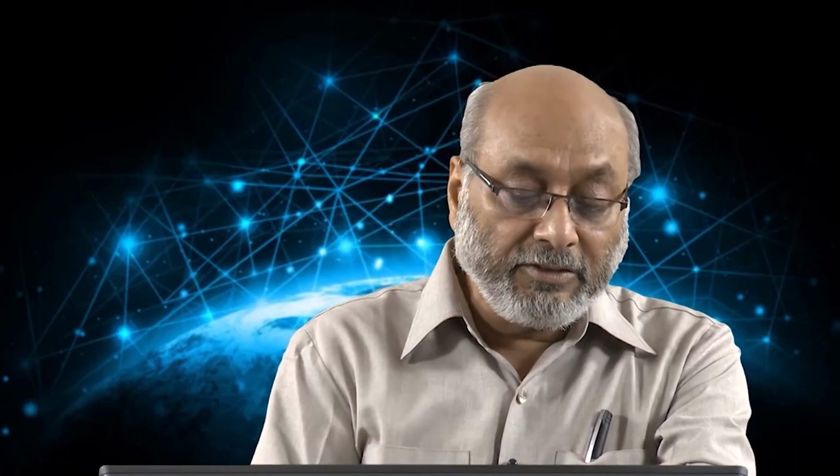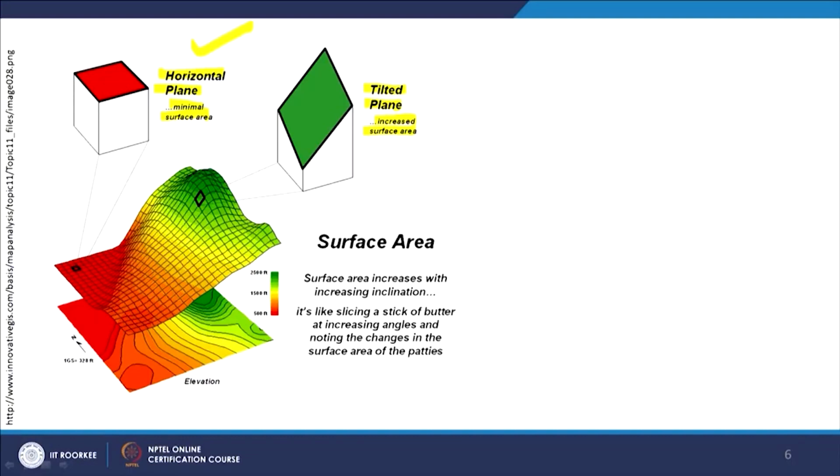So, in sloping conditions the area is going to be more. But if by mistake somebody does the calculation only using the horizontal plane, then basically he is underestimating. And I tell you, I know various projects which have failed because people have underestimated the earthwork, for example, using just a planimetric concept and assuming everything is flat, like using survey toposheets, calculating the length and area, and grossly underestimating the work. And later on such projects go into real trouble.